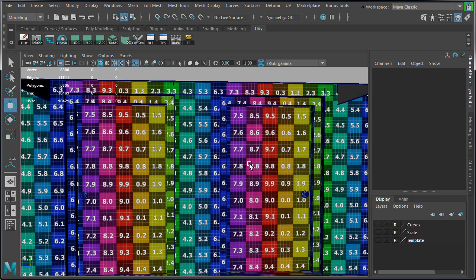The back door UVs will share texture space for the door frame, the door, and the doorknob. But we might separate the door UVs themselves to have their own UV space. If we decide to add some unique texture detail, they will have to have their own UV space. So we might have them separated when we begin arranging the final layout. But for right now, we'll leave them as is.